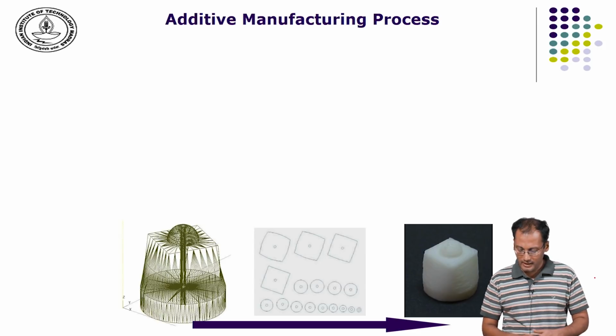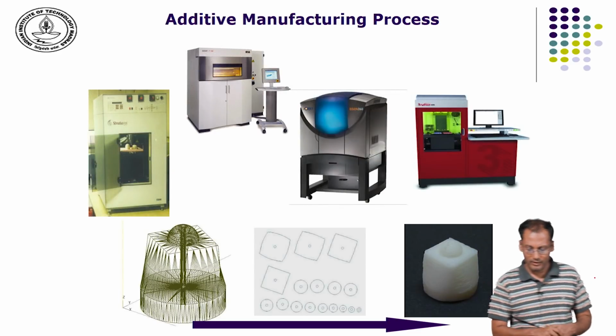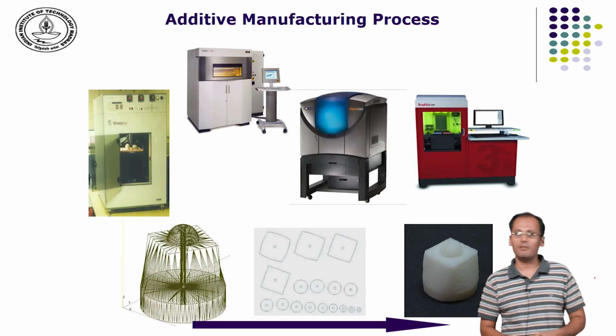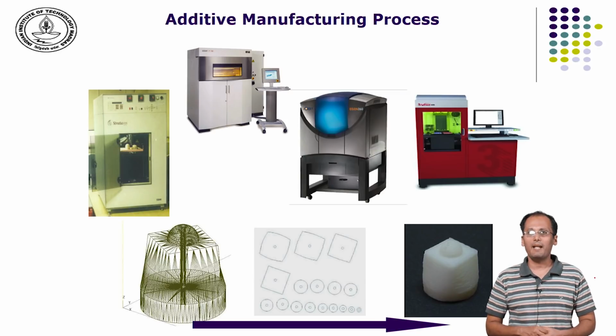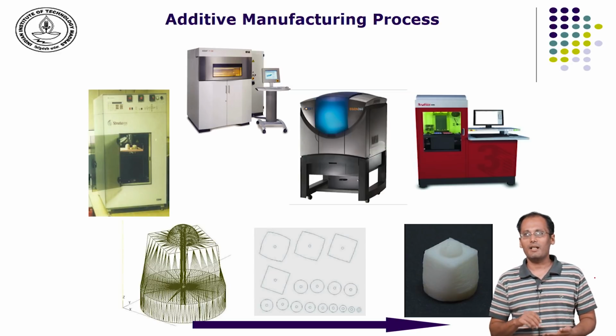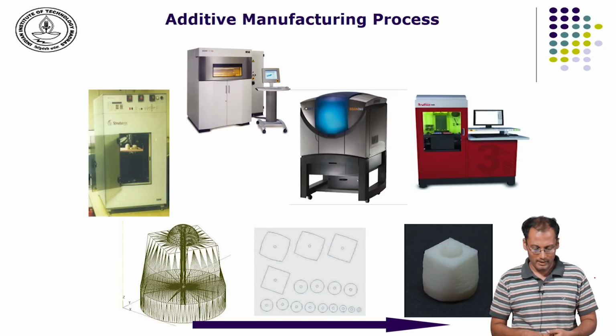And to your right, you see a part manufactured using a technology called fused deposition modeling. So, there are a plethora of technologies available. You have fused deposition modeling, where a plastic or polymeric wire is melted and deposited. The nozzle is moved on the bed to trace the path in which the material needs to be deposited, and the table moves down, and subsequent layers are built in a similar fashion.